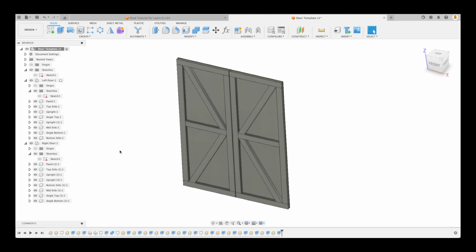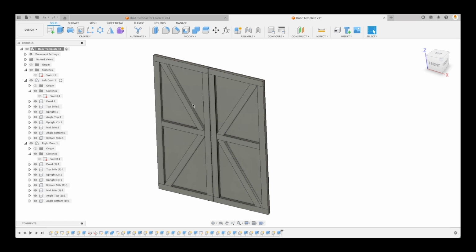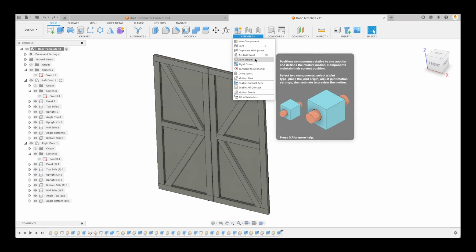Now what we can do is we have to create a rigid group. We have to say that all these components, the correct assemblies, are joined together. Why? Because if we accidentally move a component off to the side, it's very hard to work with. And we can't put any animations or joint motion or anything like that. So I'm going to undo and let's create a rigid group.